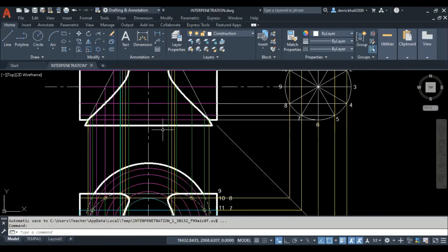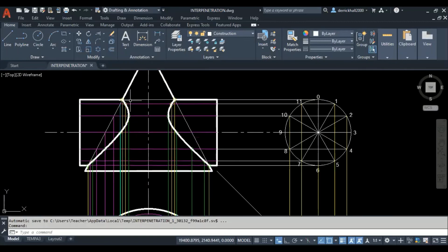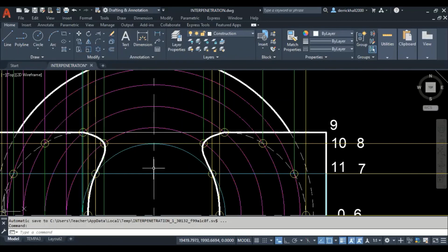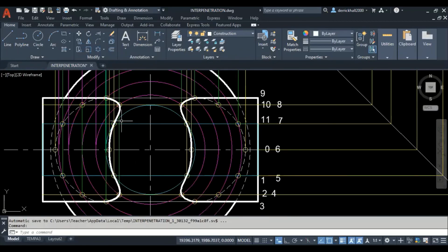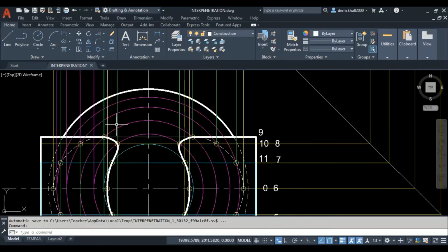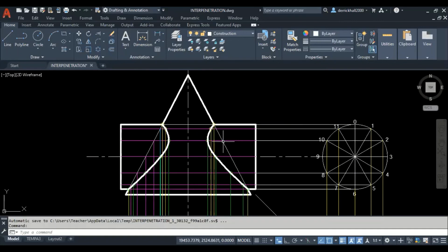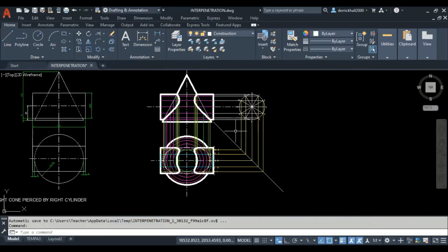Now when we cut across the cone, we see a circle. So where the circle intersects with the rectangle, we get 4 points in the plan. And we project these points back to the elevation to match the corresponding plane to get points up here. 4 actually, 2 at the front and 2 at the back. So this is our solution. I do hope you would have